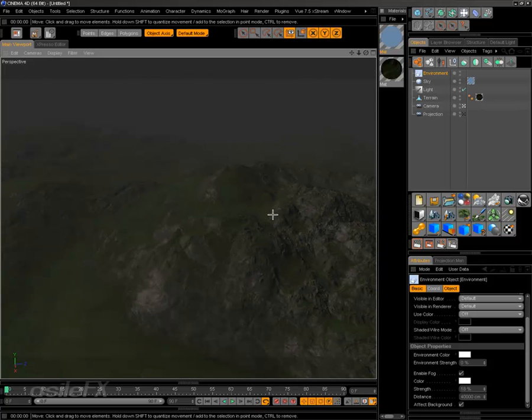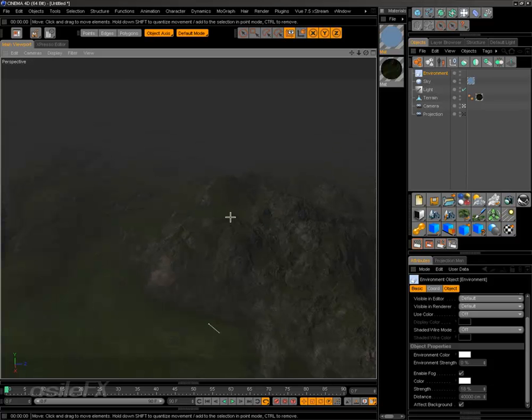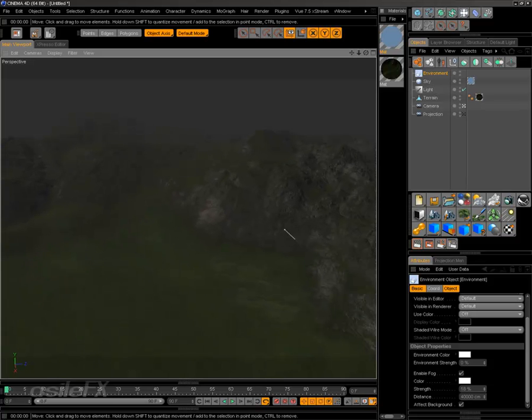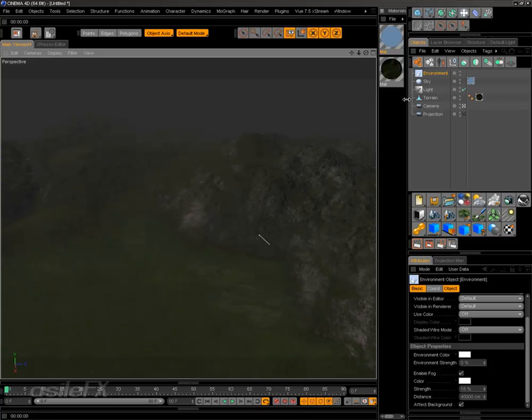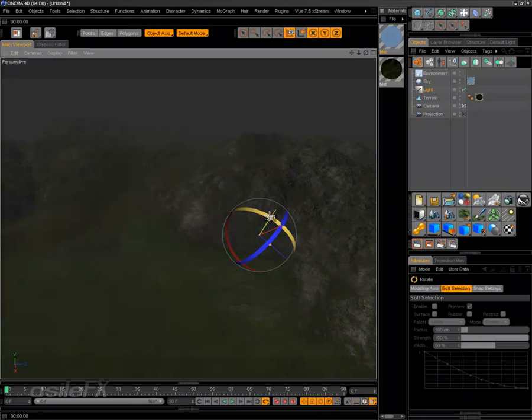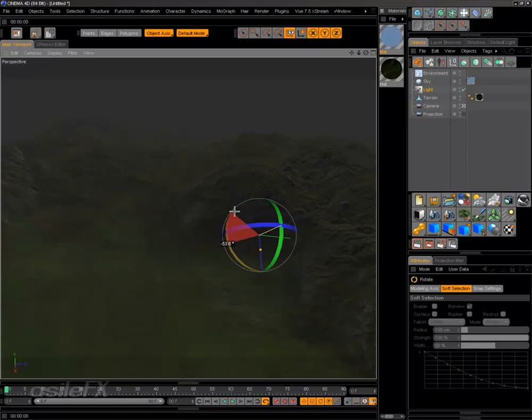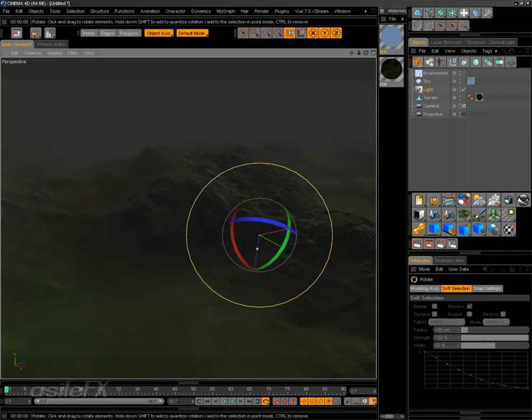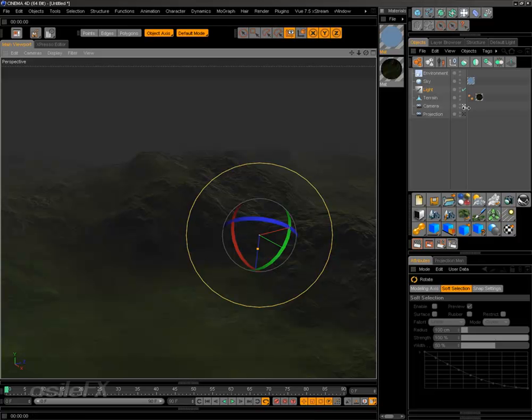I do want to note that whichever camera is the active camera within view is the one that's going to show up in Xstream. So anytime you create a new projection, what you'll need to do is make sure you have a file saved with that camera as the active camera. And then doing as I had done before, where you view from the camera and then add in a new camera to match the values.